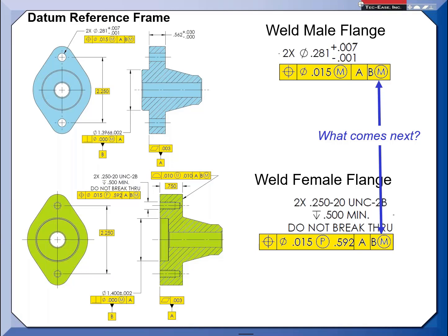Well, let me give you an example. I had a cover going on a big electronic enclosure, and we were mounting 4 fans. Typical with the fans, we had 4 holes and 1 big cutout hole. If I had used one datum reference frame like A B C on all 3 patterns, and the inspector brings that in, if one of the fan hole locations, the group moved together relative to each other, the fan would fit, but relative to the other fan holes, I've now shifted. I'd have to disqualify that part because all the features must meet the simultaneous requirement. So why would engineering want a separate requirement? Those features have no relationship to the other set, so break them apart.